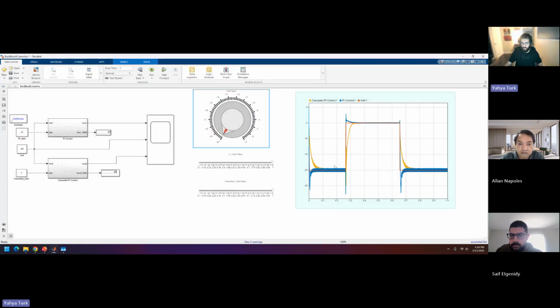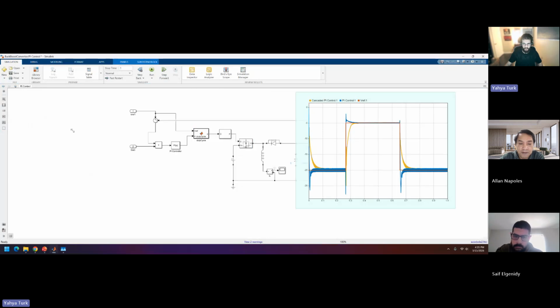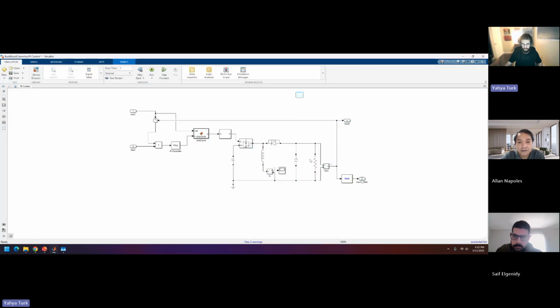So comparing both control systems, it depends. It depends on the design specification and use, but we feel like they're pretty comparable in terms of settling time. The cascaded has a lower overshoot, but at such a low load you can use either one, but we feel that the cascaded shines when we increase the load.